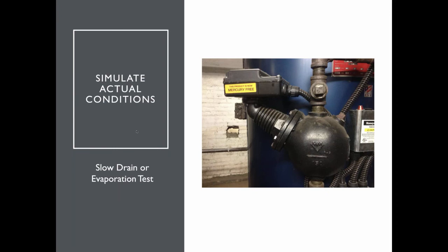And what will happen is the float will drop once you open up the valve. But under normal circumstances, if it's just steaming away, that float could stay there and run forever and the boiler could be out of water. There could be scale or mud inside here that's going to keep it open, keep it firing. So a lot of the insurance companies are asking for this.